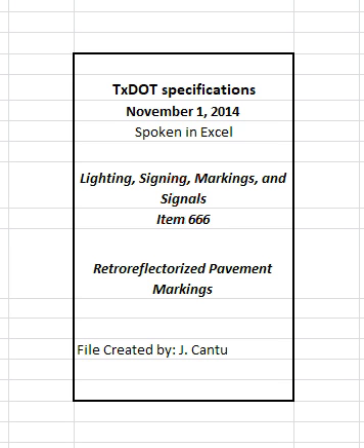When pavement markings are required to meet minimum retroreflectivity requirements on the plans, use a mobile retroreflectometer approved by the Construction Division and certified by the Texas A&M Transportation Institute Mobile Retroreflectometer Certification Program. Use a portable retroreflectometer that uses 30-meter geometry and meets the requirements described in ASTM E1710.